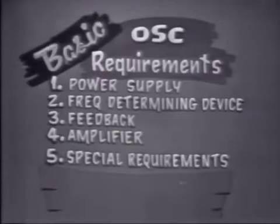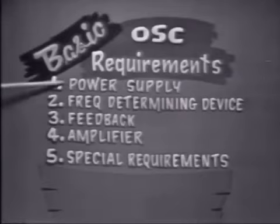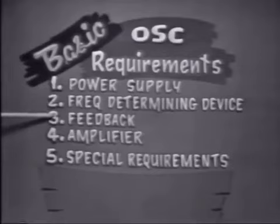So whatever the type or the name of the circuit, all oscillators will require a power supply, a frequency determining device, feedback, usually from an amplifier. Now, if you apply these basic principles, oscillators will be much easier to understand. Just like this clock, the spring drives the gears that feed energy to the pendulum, which is the frequency determining device. And thus, the pendulum moves at a constant frequency and amplitude, which, of course, is the purpose of any oscillator.